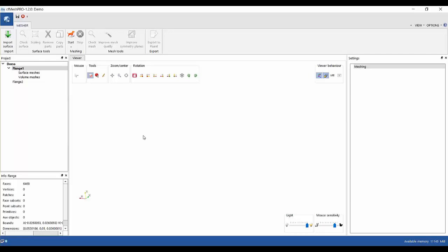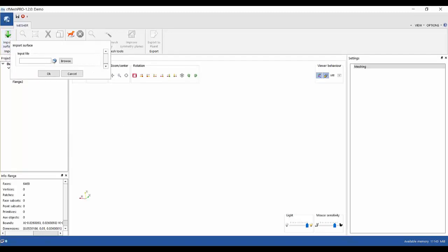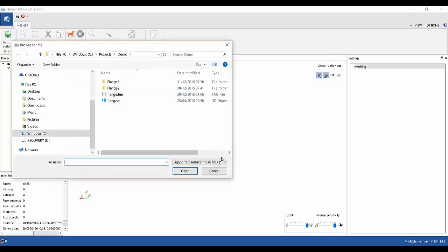At the end of this video tutorial, we will show how to use the command line editor in performing some of the previously shown steps. First, there is a utility to convert to FMS format and import into the project the surface mesh data represented in other standard formats, STL, VTK, and other. The list of supported formats can be seen in the Open File dialog box.